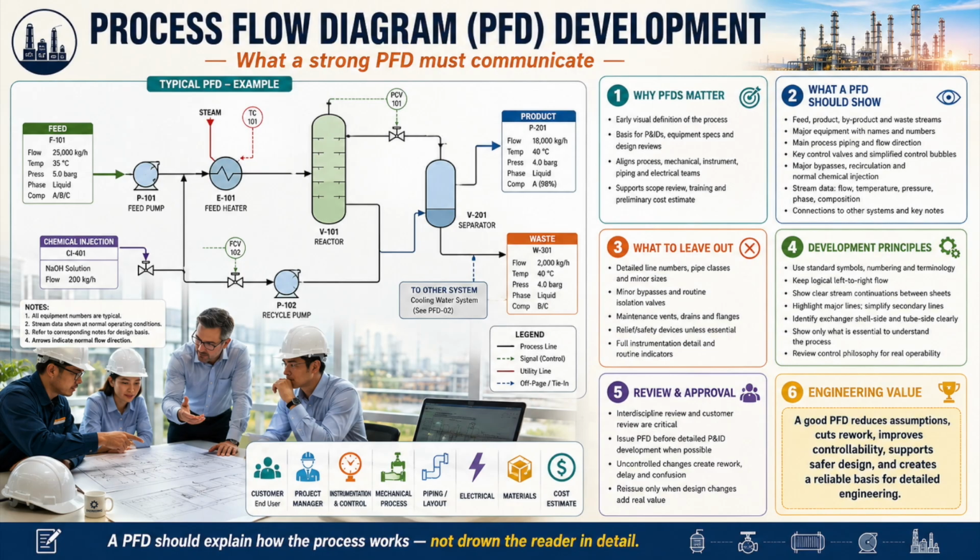The PFD should reveal the basic control schemes before hundreds of instrument tags, interlocks, and signal connections appear on the P&IDs. The mechanical engineer uses it to determine the number, type, and approximate size of major equipment. Stream duties and enthalpy differences influence exchanger selection, rotating equipment requirements, and potential supplier identification.